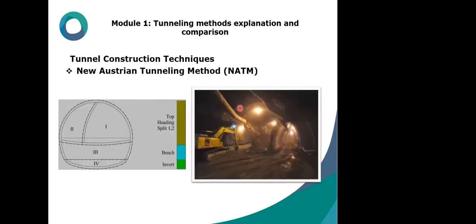And at the end of Module 1, we will go through the tunnel construction techniques, traditional and mechanized, in brief. The most commonly used tunneling methods are NATM or SEM and TBM. A designer should be familiar with both methods, although specializing in one of them. So here we will go through both methods deeply enough in order to understand the specifications and conditions of the 2 methods, and a general comparison between them.